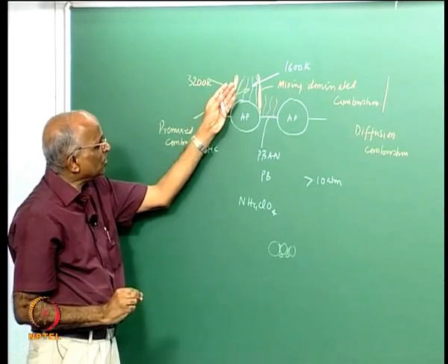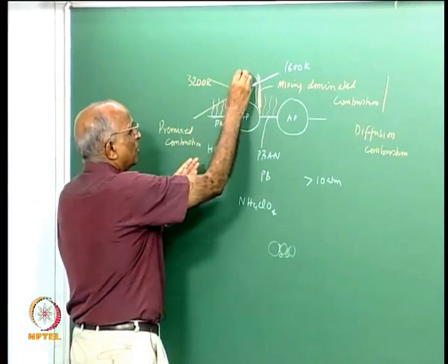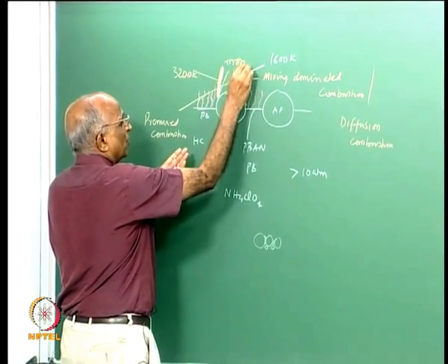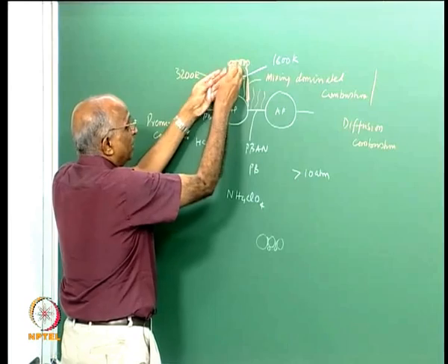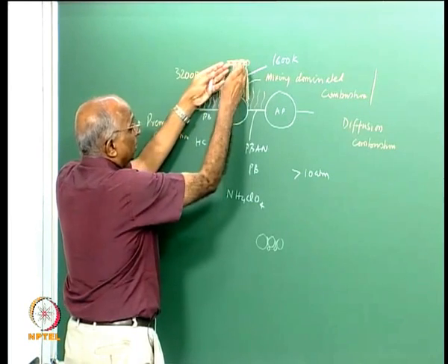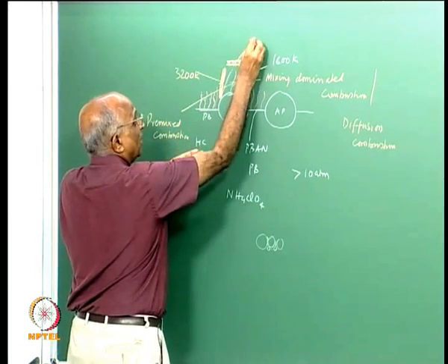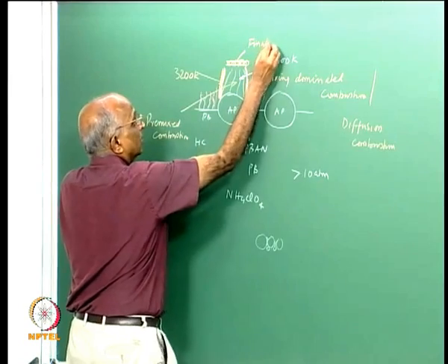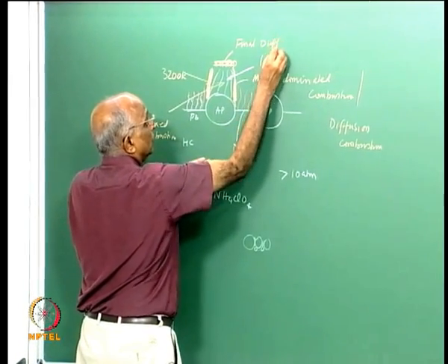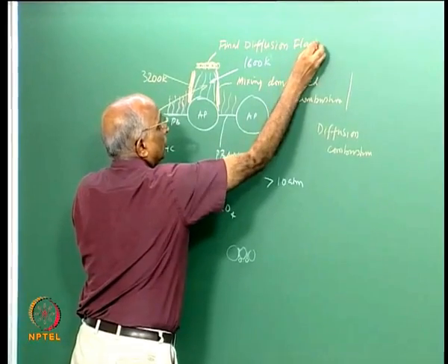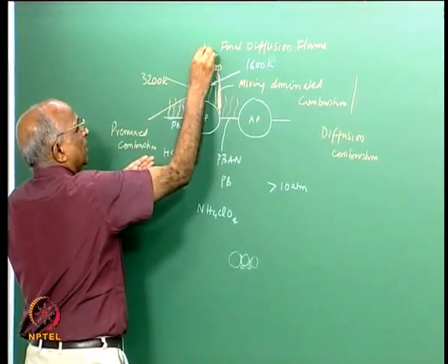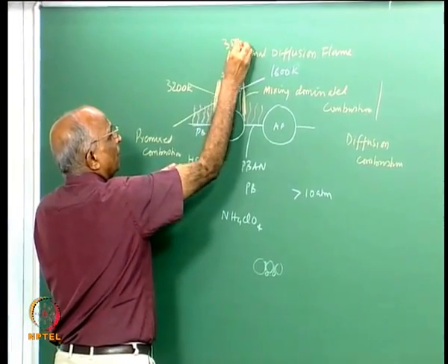Well, gases are still reacting, this is still oxidizer rich, some of these products of combustion again meet over here, products from this come over here again meet it, therefore I have another mixing combustion here, and this is the final diffusion flame. And the temperature here is typically around 3500 Kelvin.